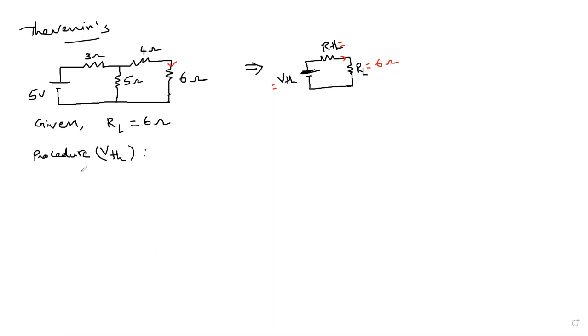So how to calculate VTH now? What is the first step? You should open the load resistance, RL. Open the load resistance. Done.